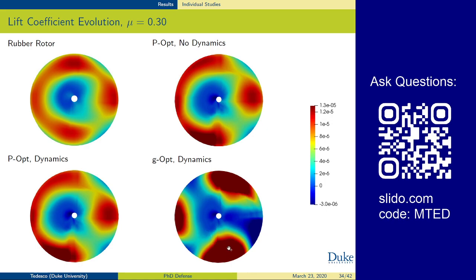Also interesting is if you notice, this is a heavy 3 per rev, and if you remember back from our table, there was a significant 3 per rev increase in controls. So this is in alignment with what we saw in the control evolution when we did vibration optimization.